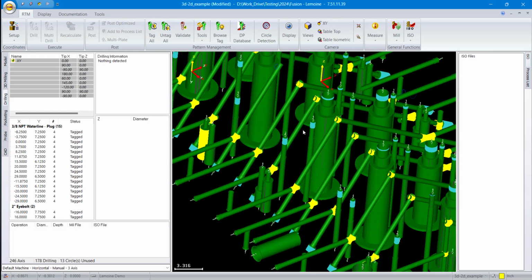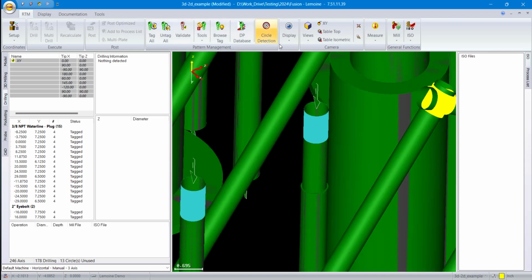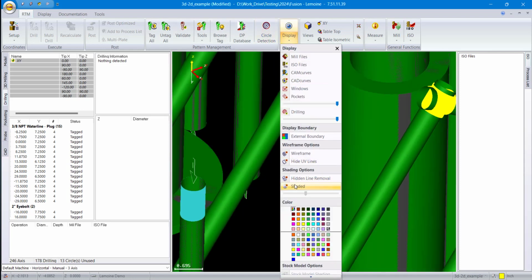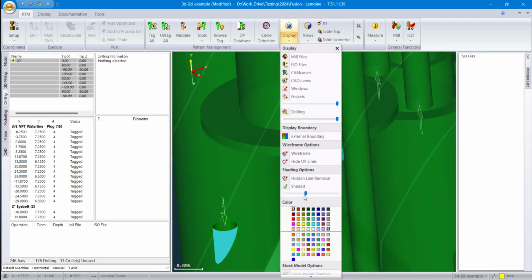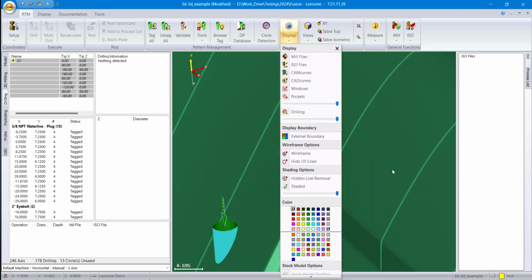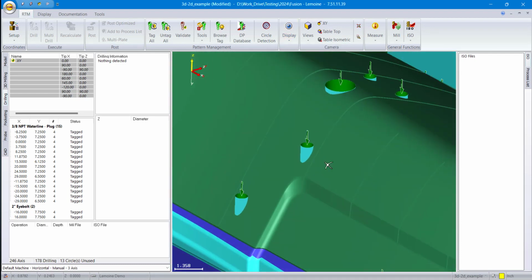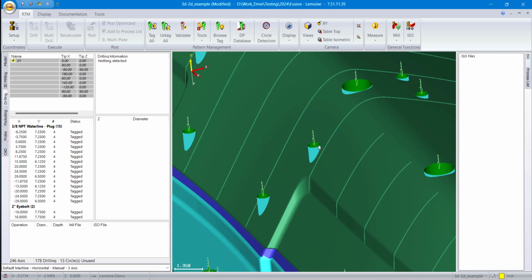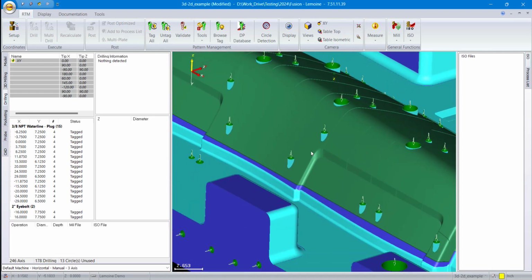These light blue areas are what we call the ellipse. If we were to pull on the model for a second, I'll darken it up a bit. These are ejector pins that are coming through the front of the job, as well as some nozzle drops. What we do is find the high point for drilling. There was an ellipse sitting on the part here, and we've extended that out to the high point of the ellipse to make sure that when we start our drilling, we actually start in the right spot.